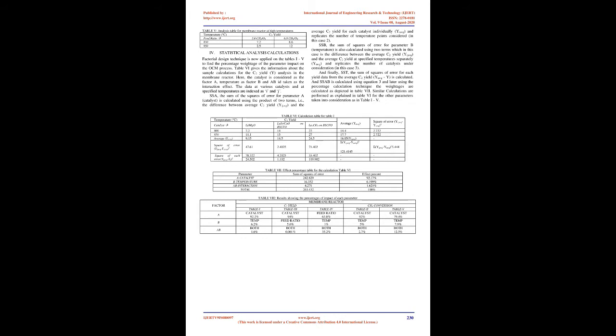But apart from the other researchers, Pacharavorakot around 2014 took a different approach by considering a mathematical model of the OCM process coupled with the kinetic model to examine the performance of OCM in membrane reactor in terms of CH4 conversion, C2 selectivity, and C2 yield. He conducted a simulation study using OCM membrane reactor operated at higher temperatures and lower feed ratios. CH4/O2 can improve C2 production. Here simulation results are compared with the experimental values chosen from Stanch et al. 1997. The values from their research works are compiled into analysis tables as depicted in Table 1.